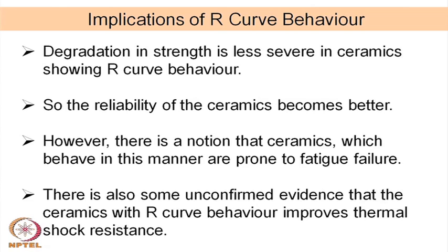In general, as you know, because of the low thermal conductivity of ceramic materials and poor fracture mechanical properties, ceramic materials have less shock resistance, but the materials which have R-curve behavior, or toughened materials, do improve the thermal shock resistance, which is kind of expected of materials with improved properties.